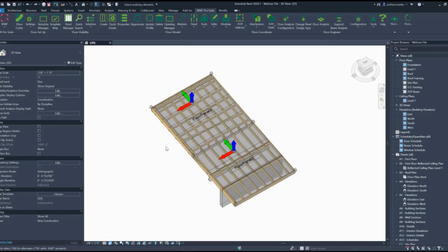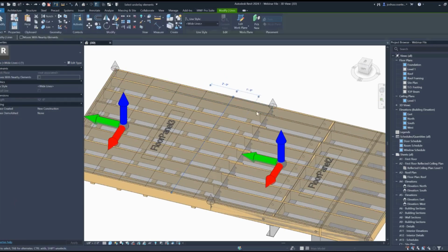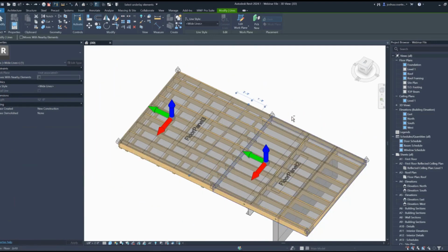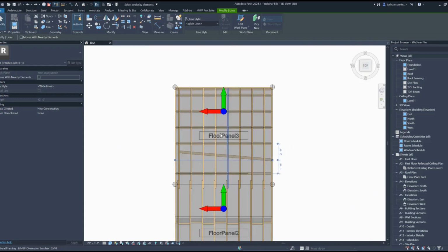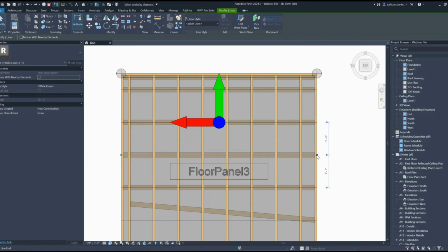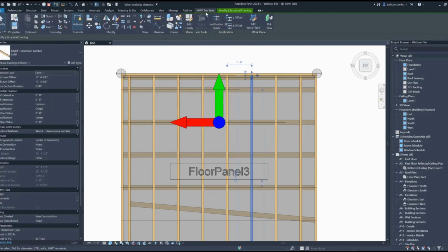And the last thing that I want to showcase regarding the marker lines, this applies for both hole series and bridging types. You can actually modify where the line stops. So now that I've created all these different marker lines, I could say maybe this piece of strapping is fine to stop here. Let's stop one in the middle of the bay. I want to show you what happens there. And we'll do another one back here. And I will regenerate.